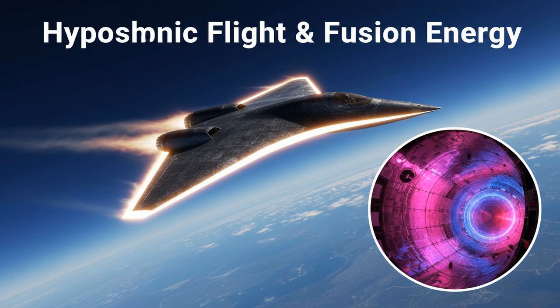The solution is ceramic matrix composites. Vehicles like the X-51A Waverider use carbon-carbon or SiC-SiC composites. These black ceramics do not melt. They ablate or insulate, keeping the internal electronics cool while the skin of the aircraft glows white-hot. For the sharp nose cones, which take the brunt of the heat, we use ultra-high temperature ceramics like zirconium diboride reinforced with SiC.